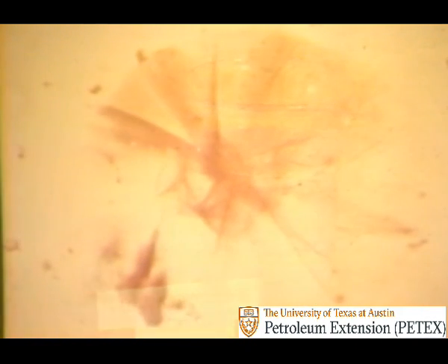This is a particle of bentonite or sodium clay taken through a microscope and enlarged 35,000 times. It is flat, platy, and looks kind of like a fanned-out deck of cards. It is this flatness, plus the particle's extremely small size, that makes bentonite good for filtration control.